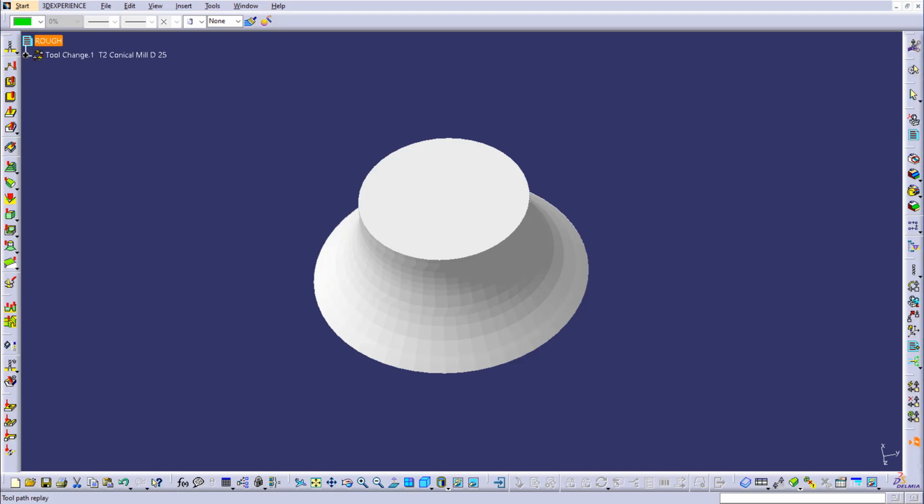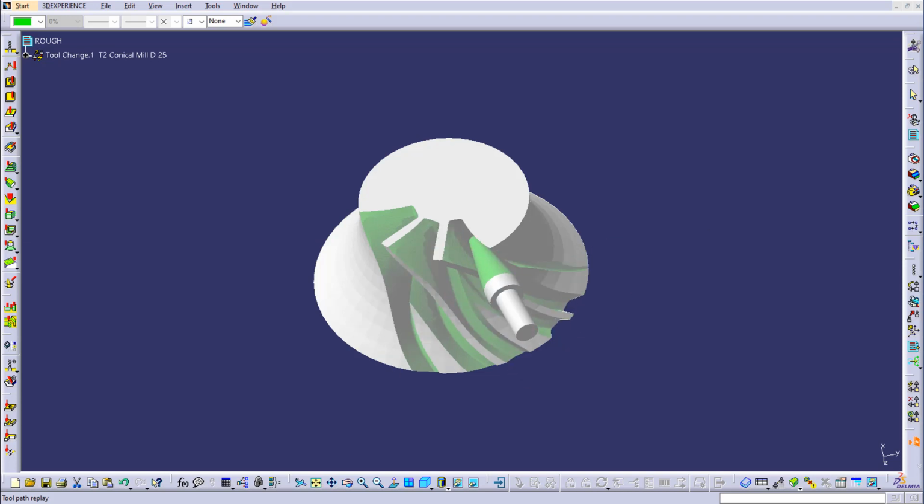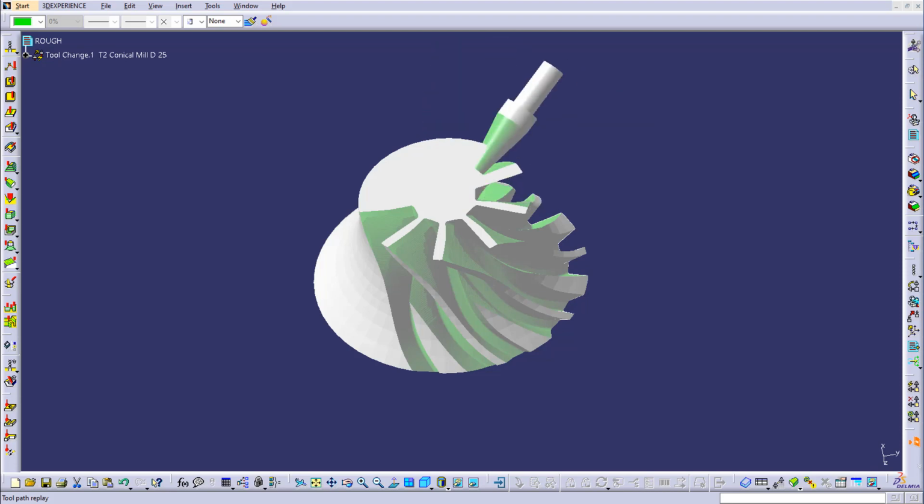At this point, additional programs such as VeriCut can be used to increase the efficiency of the G-code and cutting process to reduce cutting time and improve overall productivity. The final and optional step is to create a Catia scene where a complete rendered video can be made of the cutting process that shows the part and tool models in action.